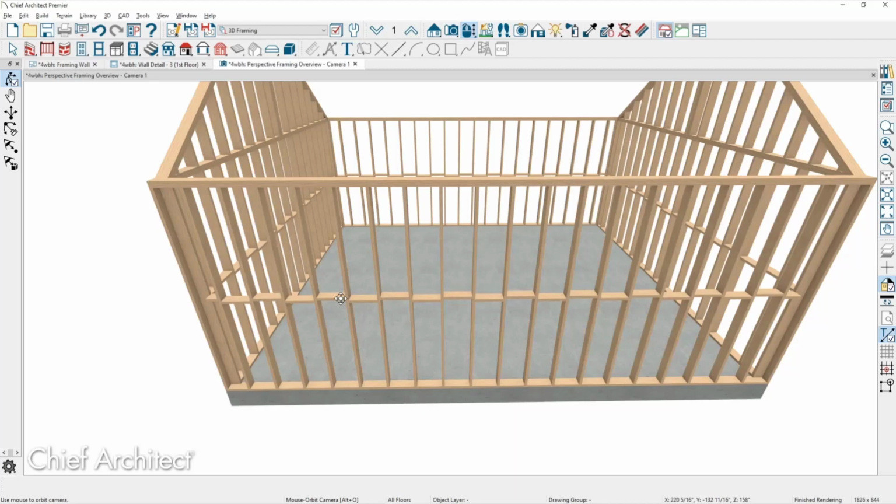You know, one approach, if you don't like doing it on every wall, you could do it on 1 wall and just show it as a detail that said, you know, all walls to be blocked per this detail, and you run your dimensions to show exactly where the blocking occurs. Yes, could do. Okay, thank you for that.